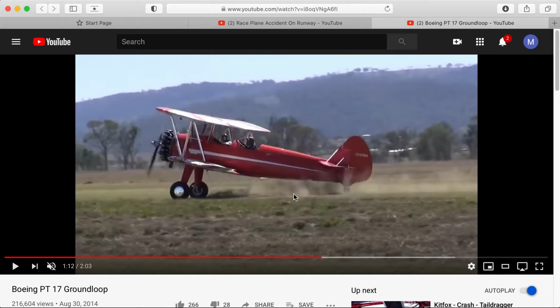And just one thing after that, once this thing starts to go, it's really hard to recover after that. The tail wheel is not doing a whole lot of good to help keep it pointed down the runway. It started going off the left side of the runway. You see the weight start to shift over here onto the right wheel.